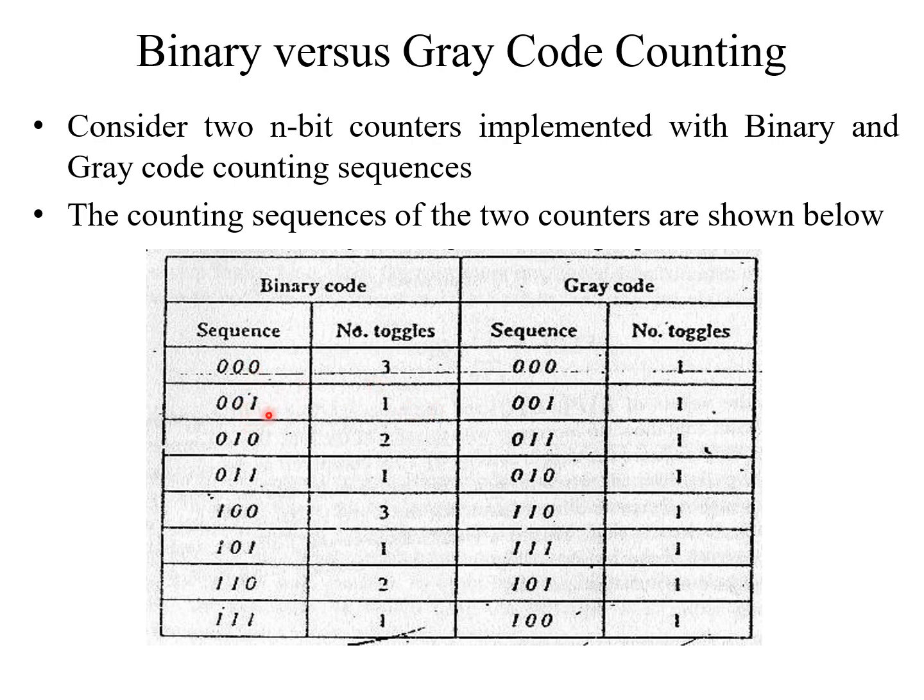Here no bits. Here one bit, that is 0, only 0 to 1. Here 3 bits. Here 1 bit. Here 2. Here 1. If you take the gray code, there will be only one bit change. From this to this, one bit change. From this to this, one bit change. From this to this, one bit. So between the previous state and the present state, there is only one change. Okay, but binary is not like that.